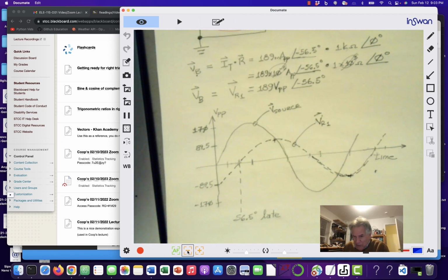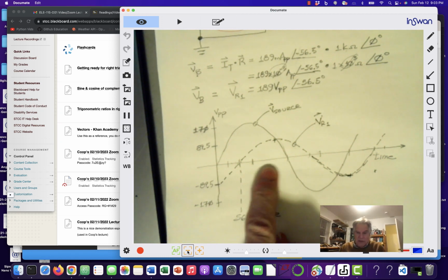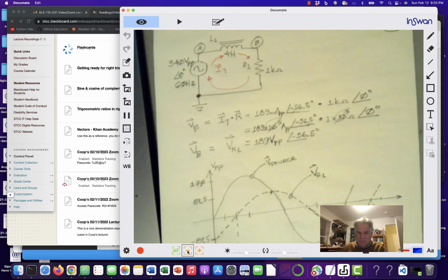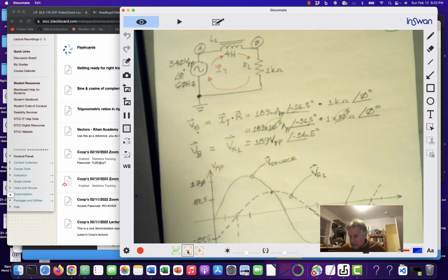So you take a sine wave. We'll see this, but my point is, you can break any periodic waveform into a bunch of sine waves, and you can now analyze what a circuit's going to do at a given frequency with sine waves. If you automate this in a computer program or a spreadsheet, you could put in some low frequencies and see how they do, some middle frequencies, and some high frequencies, and gain a lot of understanding. And you didn't need any calculus at all.